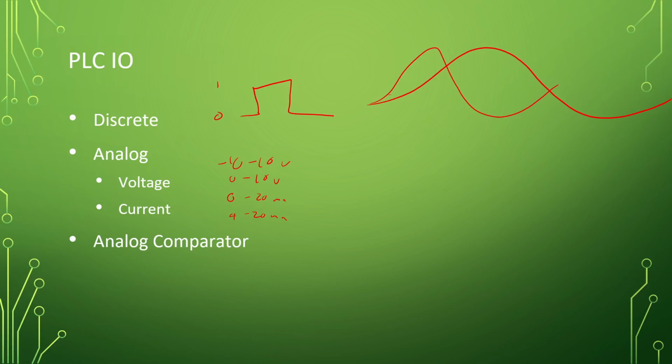Whereas if you use 0 to 20, or even that 0 to 10 volt range, and it's 0 volts, like the bottom of the sensor range, your PLC goes, is it there, or is it just reading that there's no liquid in the tank? So that is a game that you have to play. That is why, personally, I'd go with the 4 to 20 milliamp option, because it allows you to detect that, yes, my sensor is actually existing.